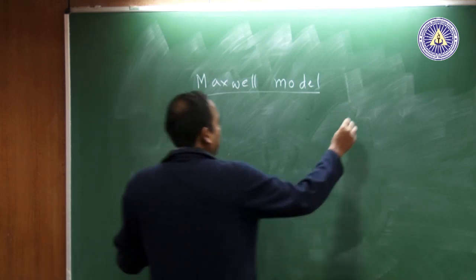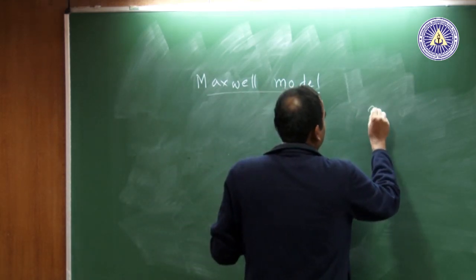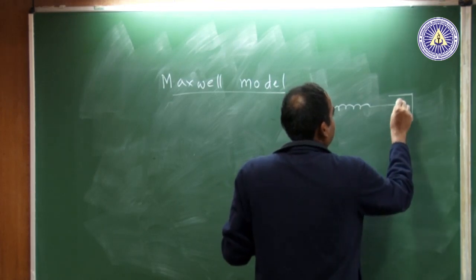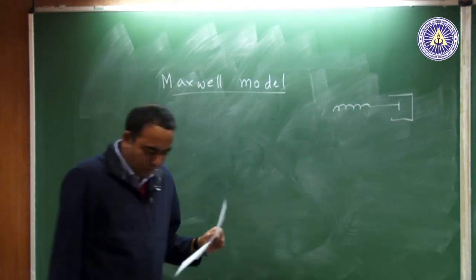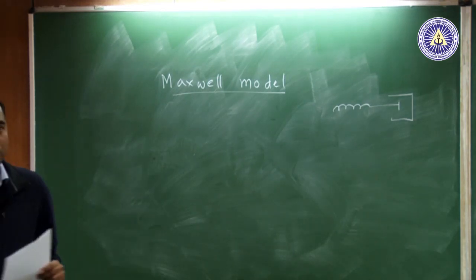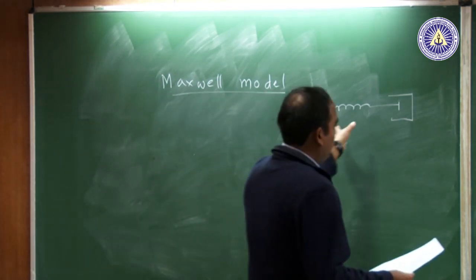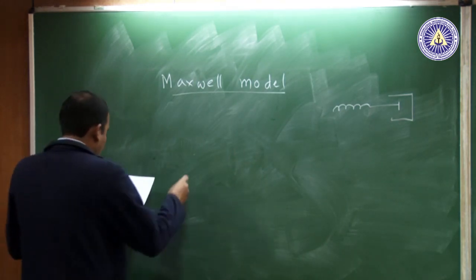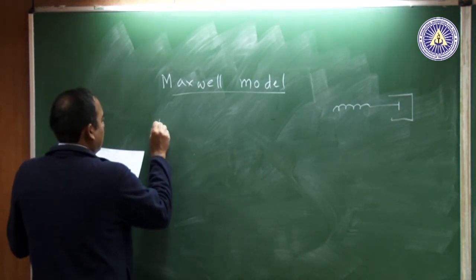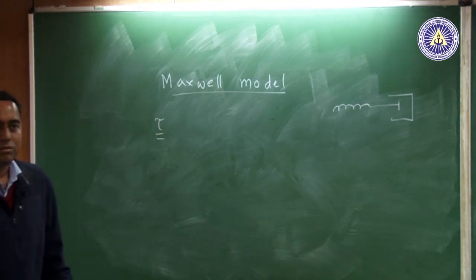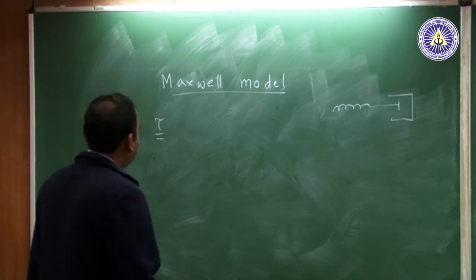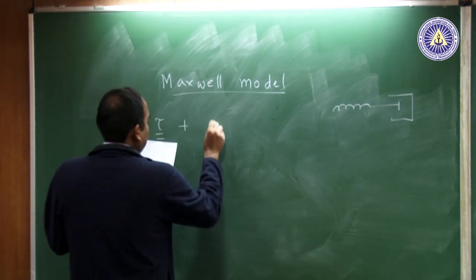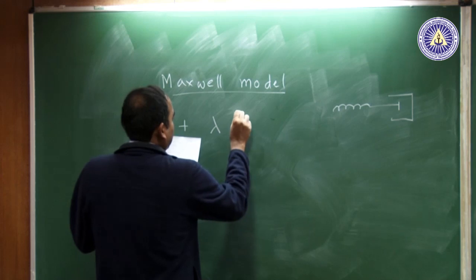and he would have said that a Maxwell model means there is a spring and then there is a dashpot. So, if you have a viscoelastic material, you can model the viscoelastic material as a series of spring and dashpot. If you have a single spring and a single dashpot, you get the following Maxwell model. If you convert naively to a tensorial form, the same Maxwell model, which involves a spring and a dashpot, in the tensorial form this would come out to be true.